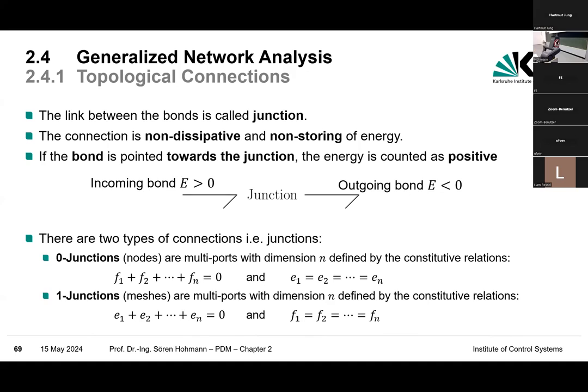And we are used to work with equivalent circuits, where if you do, for example, nodal analysis, where you look at the Kirchhoff's laws of one node, then you draw into your pictures the direction. By the way, it's important. At that point, you have to decide what kind of direction you count positively. The only thing is you should not mix everything up. So again, stay on the same sign convention. And then you find the nodes.